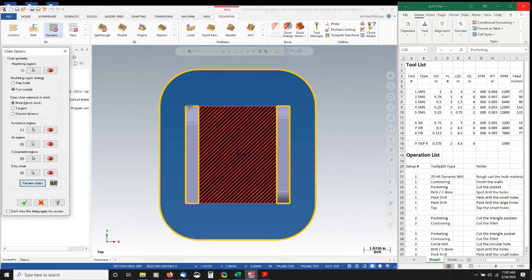The thick yellow lines are lines that your tool will not cross. So they're hard boundaries, they're walls. So you have a few sets of walls here. You have walls that are now protecting your remaining material, which has been defined by your avoidance region.